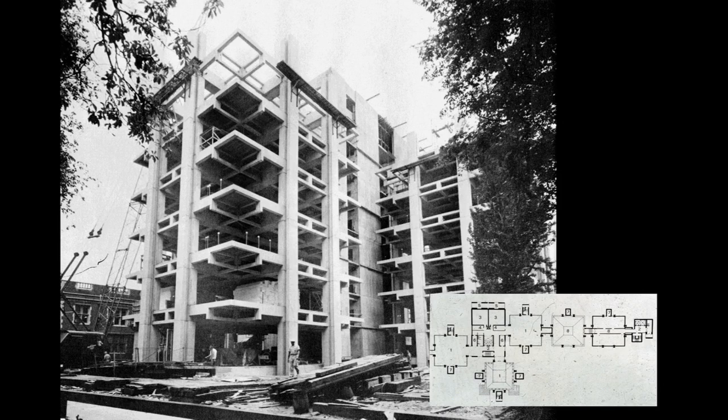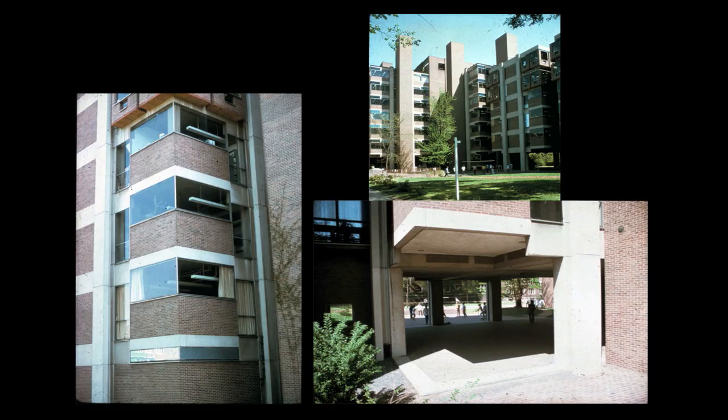the outside extent. And so what we see Kahn doing here is innovating the structural system to diminish the amount of material at that outside cantilevered corner, thereby lightening the load, but also expressing how the loads are being resolved within the structural system. And so the building ends up having this very interesting corner detail that shows Kahn's understanding of the structural system and shows how it could be manipulated to be expressive structure as well.